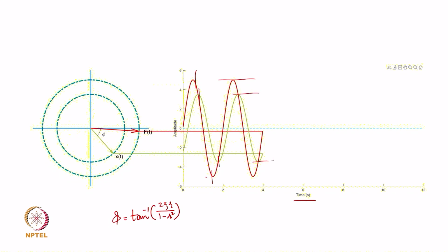So, maybe we will be interested in knowing the peak to peak or response amplitude; whether it lags by 20 degrees or 40 degrees may not be so relevant in general, but it has its own role, particularly in some applications, like when you are trying to balance a rotor or in balancing processes, where those phase values would be of significance. It also helps in understanding the vibration phenomena better, as we shall discuss in the base excitation case.